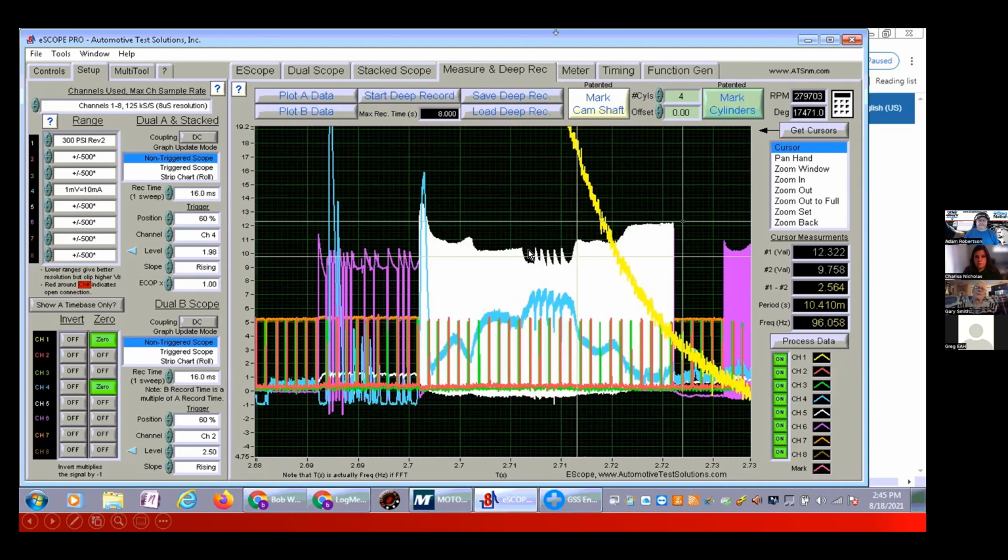And what it does is it reboots and it looks for 500 microseconds for these same readings. And if it sees it, it dumps it out again, and it rapidly tries that. And it says it in the data sheet, guys, and this is why I got excited to show this to you today. It drops it out 5 times, and then it shuts the driver off after the 5th check and sets the fault. Look at what we have here. 1, hold on, 2, before you go any further, Gary. 3, 4, 5. So let me bring something up. You've got the 5 dropouts right there. That's pretty cool. And it meets the chip trying everything to reset. That's right.